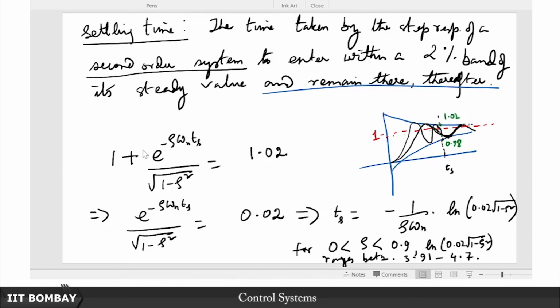Okay. So in fact, this real part of the pole, after all it has the units of frequency, is also called the Neper frequency. When you have the imaginary part of the pole, that can easily be correlated with the frequency of sinusoids and cosinusoids, but this real part appears as part of the real exponential. So you do not generally think of this as some sort of a frequency, right, but it turns out this is also called a Neper frequency, and this basically dictates how soon your transients are going to decay. Just like your ordinary frequency dictates how many times the oscillations will occur within a given time period, right.